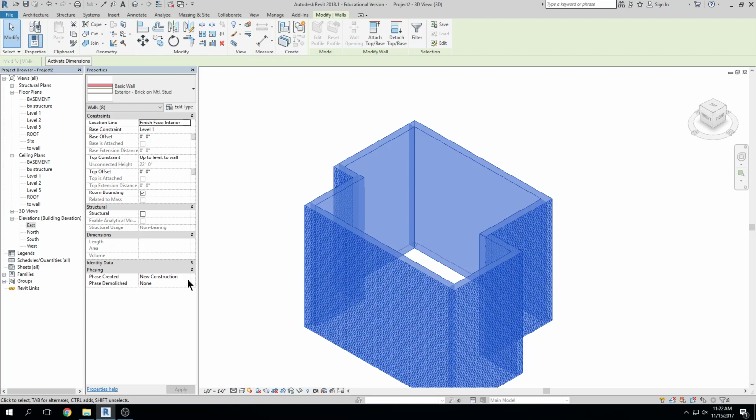Could your walls be pinned to that CAD file? They won't be pinned to the CAD file, but you can pin them in the spot they're in, which correlates to the CAD file. So you can't pin one object like the walls to the CAD file, no. But once you get them correct, you can pin their location. Because whenever I tried to move a wall, it would move the other wall on the other side. Yeah, maybe somehow you've locked them. So I'm having the hardest time with that. Okay. Well, let's see if that happens in here, and we'll try and figure it out.